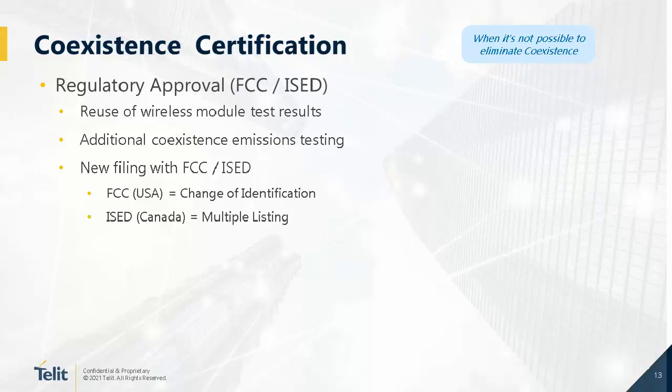So very straightforward. When it comes to coexistence, certification is also very manageable, but there are some additional steps you need to take. As long as the wireless modules have the modular FCC and ISED approval, you can reuse all the test results, all the transmitter test results from your module provider. You will have to do some additional coexistence testing, and this really makes sure that you don't create additional harmonics. This is, I would say, low-risk testing.